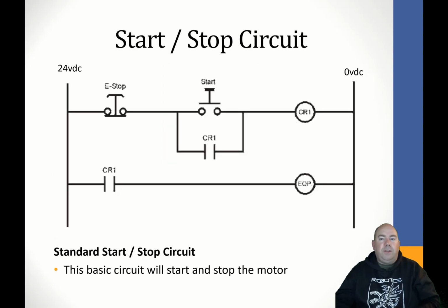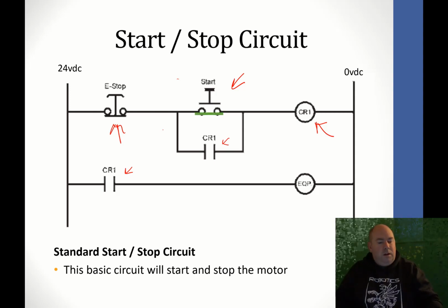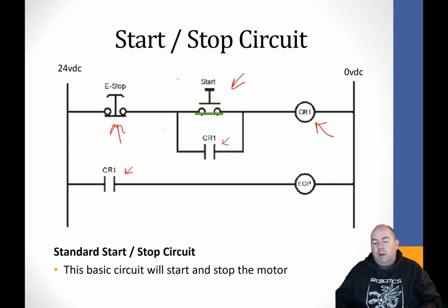And then this is our basic safety circuit. So we'll learn how to draw this. This is a single channel circuit with no monitoring. So we have here a stop button, a start button, one relay, and the contacts of that relay are used here and here. So basically what happens here, if you push this start button, that closes this circuit. Closing that circuit now energizes here,